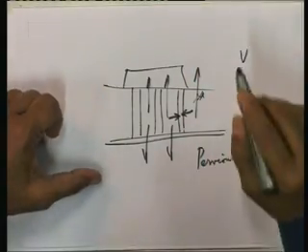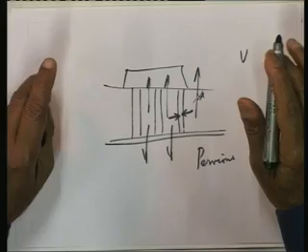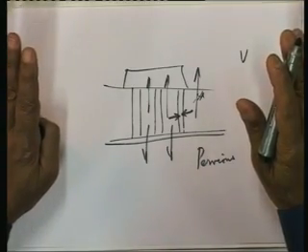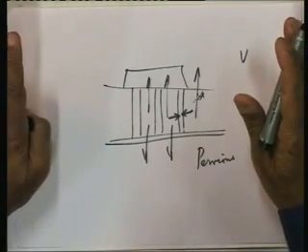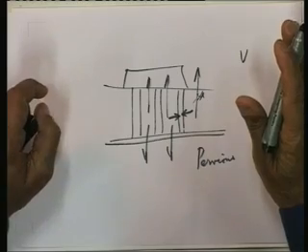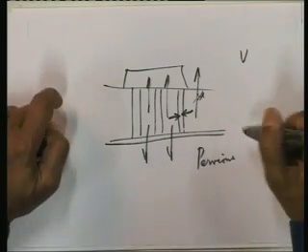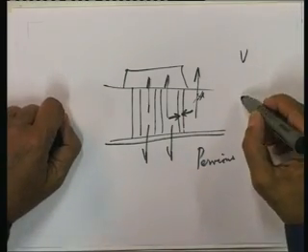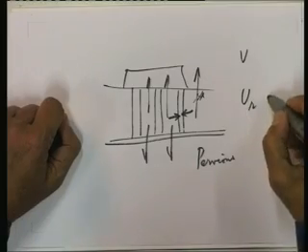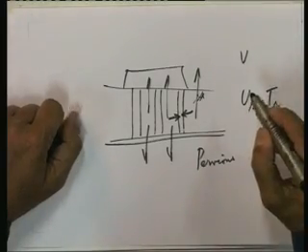The vertical component is straightforward, can be computed by the same one-dimensional Terzaghi's consolidation theory which we had seen in very great detail and for which we had seen a few examples as well. The radial consolidation also we discussed, where we calculated UR as a function of time factor TR.